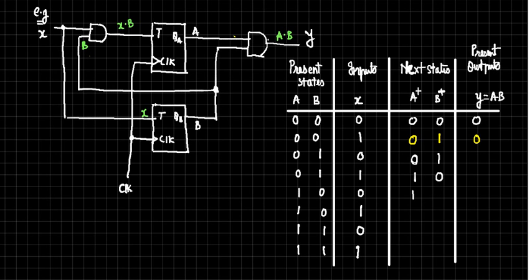Let me write, verify the states. You should get something like this. Are you getting these states? 1 0 1 0. 1 1. 1 1. Next, tell me the outputs here. All 0, and here 1 1. Is that okay? Draw the transition diagram.